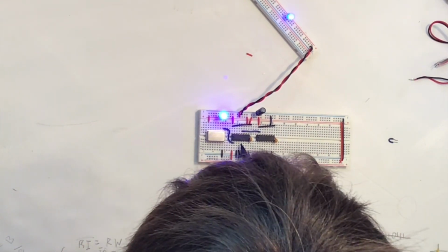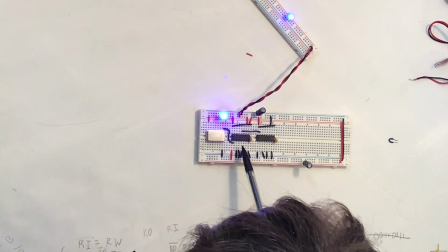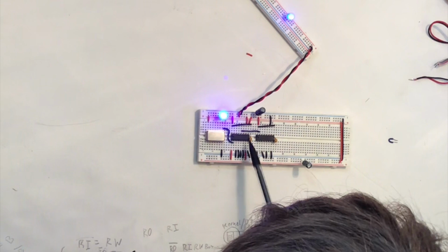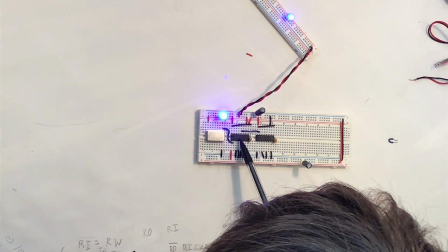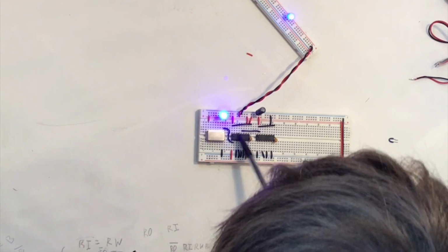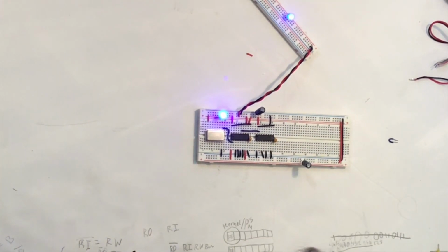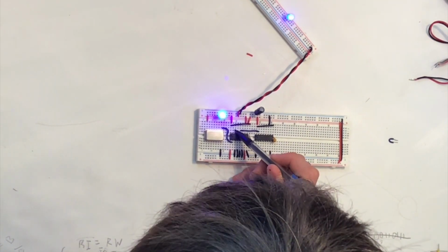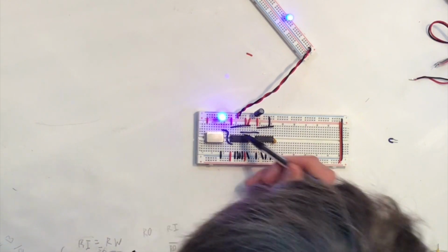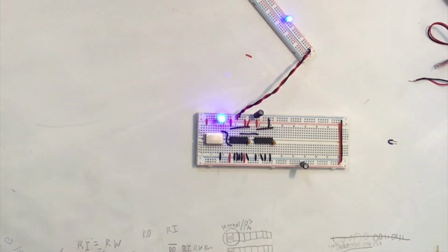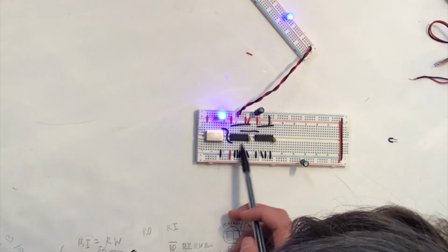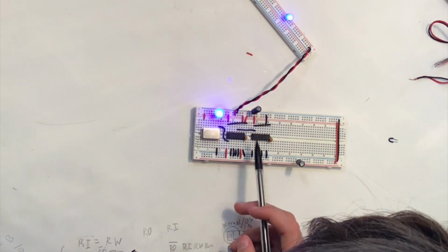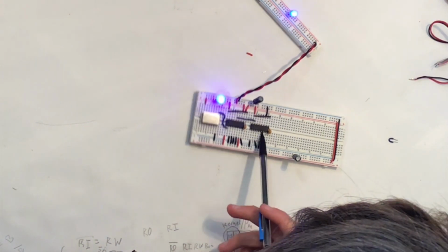This is the 74161 AC, and that's the logic. I'm using mostly CMOS, HC, AHC, and AC. This is the 74161 counter, and it works as a clock divider when I used it here. So I have the 10 megahertz output, 5 megahertz output, 2.5, and then 1.25 megahertz output. That's the main purpose of that. There I have decoupling capacitors, standard 0.1 microfarads.